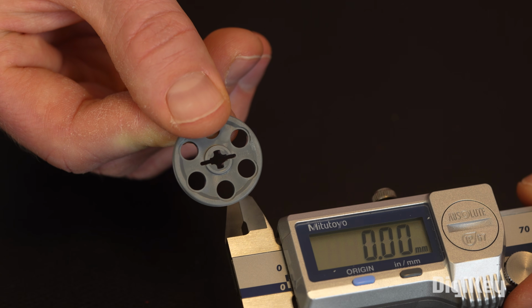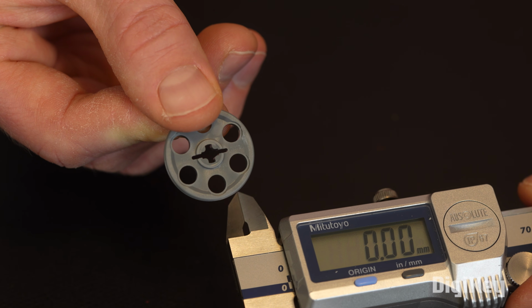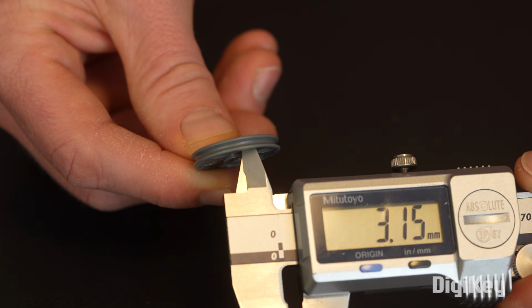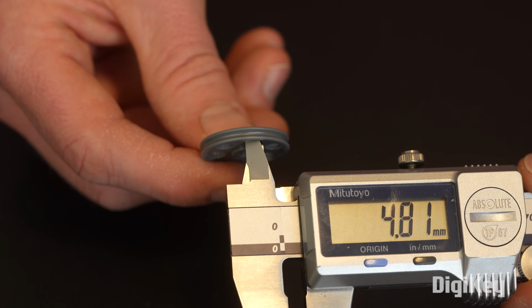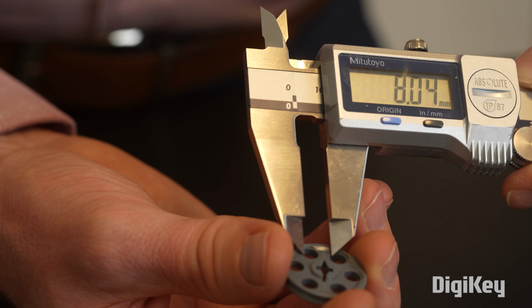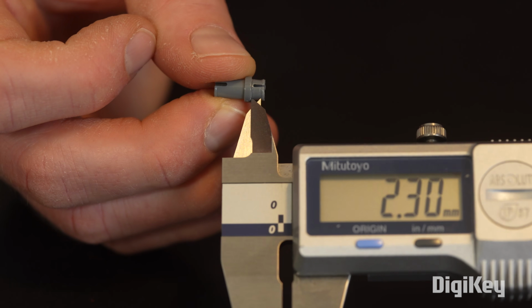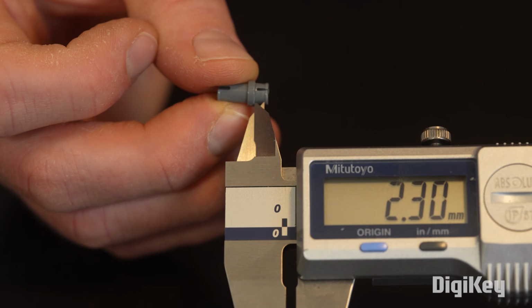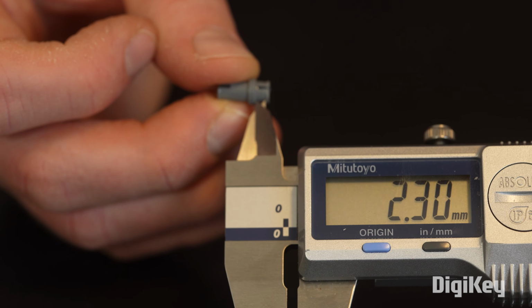We'll be mimicking this Technic belt wheel, but turning it into a servo shaft attachment. The holes are 4.8 millimeters in diameter and about 8 millimeters apart. To use these 3/4 pins, we'll need to make the disc about 2.3 millimeters thick.